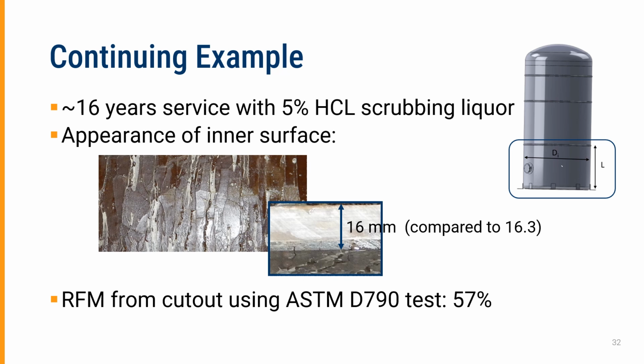The appearance of the inner surface, well, looks like this. Looks pretty rough. And in fact, you can see all of these cracks here. And you see how the cracks come up. You can actually see in this one how the crack has penetrated into the surface and then it's starting to turn. We don't have any visible cracks in this cutout behind this discolored zone.